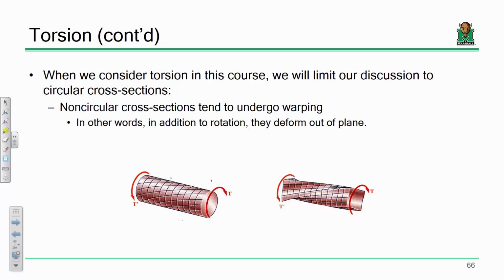And the only way that it can handle that failure is by kicking out and twisting a bit. It undergoes a particular failure called lateral torsional buckling. And so you have to understand a little bit of the mechanics of torsion in order to understand that math. But fortunately, a lot of that is already solved for us, and it ends up being a pretty plug-and-chug expression. But just in general, as civil or mechanical engineers, if you're going to have something that's going to be twisted, make sure it's circular, either a shaft or a pipe. It's very, very, very important.